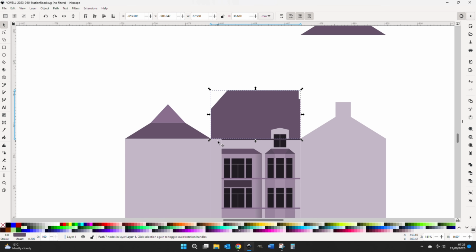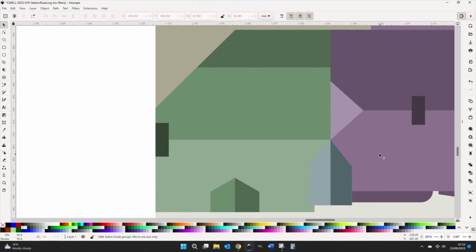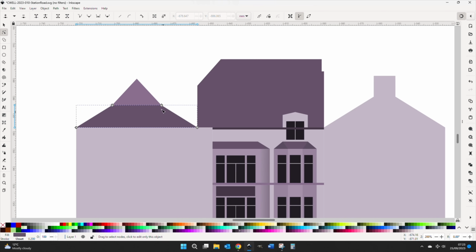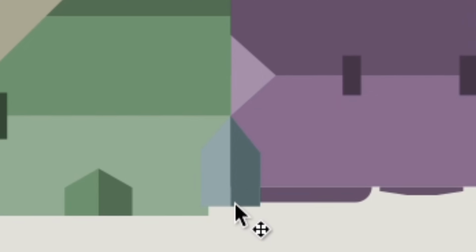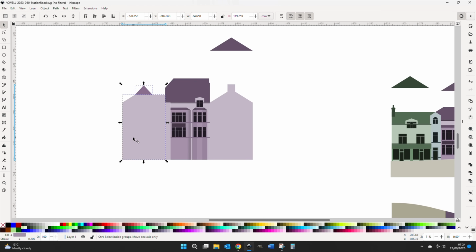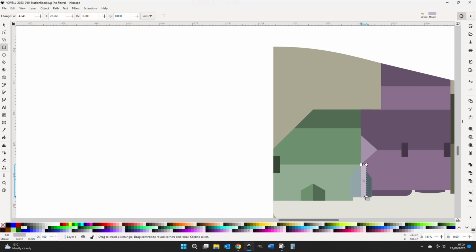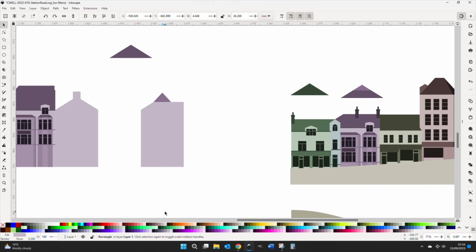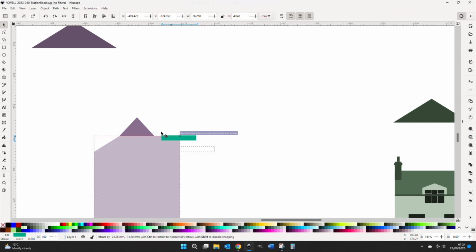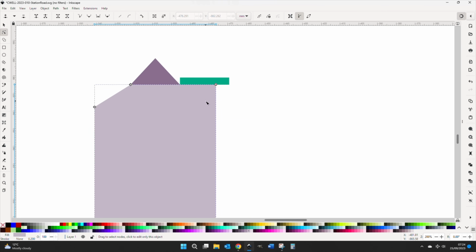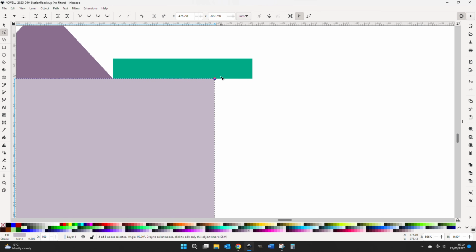Brilliant! Let's not forget that this side projects to the front of the tower here. Let's just drag this node over to align with the front face. Actually, it projects beyond the front face, so let's move the component over here and away from the fold line. Measure a rectangle from the hip triangle to the tower front. Rotate it, align it with the hip, drag round these two nodes and align with the rectangle.